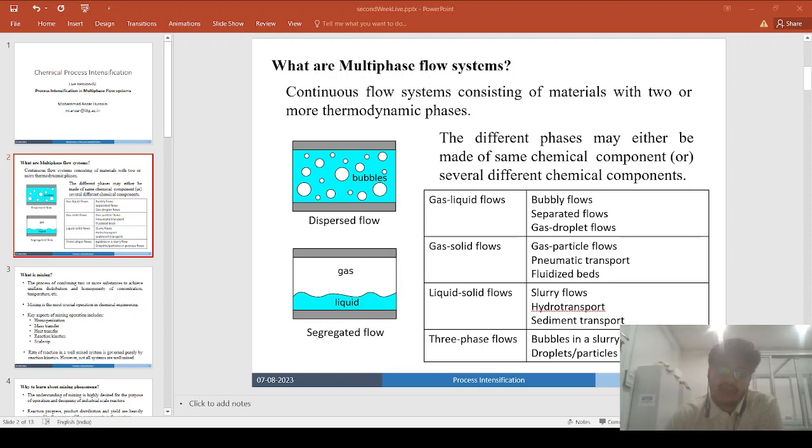Now, reactive distillation operation provides a promising process alternative to the traditional sequential operation. The potential advantages of reactive distillation are new and less expensive products, higher efficiency because of overcoming thermodynamic and kinetic limitations, better selectivity due to suppressing undesired reactions, avoiding hot spots, higher raw material conversion, savings due to smaller equipment, and less environmental pollution. These are some of the potential advantages of reactive distillation.